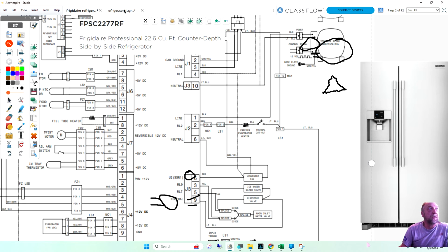Gotcha. Okay. So if the control board was damaged from that section on the control board, can it be repaired directly? A lot of boards can't be repaired, but here's a couple of things. One, unless you physically see what's bad, you don't know if it's a resistor or part of the circuit or whatever. And think about this. If the board failed and you attempt to repair it, let's say it takes you 30 minutes to take the board out, determine what's wrong, solder, repair, change a relay if you even had it, and then put it back in, how long can you guarantee that board for?